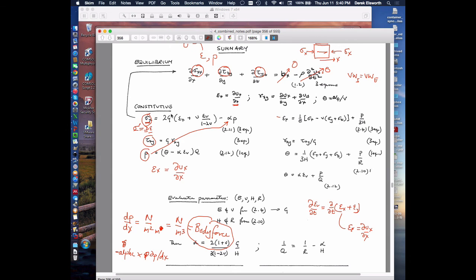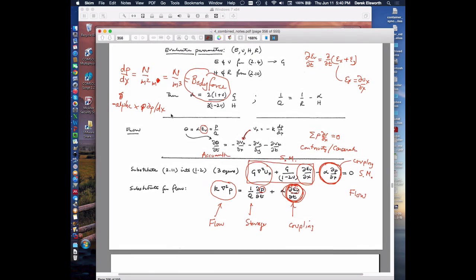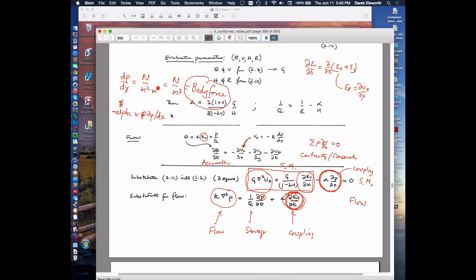But you get the basic idea. I think it was perhaps more obvious how to do it when we talked about dual permeability systems, but it's the same idea. You have to work from the PDE, you figure out what the transfer coefficients are for these off-diagonal terms. The two off-diagonal terms we have are for these components here, which in a mechanistic way is the amount of fluid which is squeezed out or into the system by deformation, and this is the body force which is applied by the fluid pressure within the system, the body force acting on the solid mechanics part.